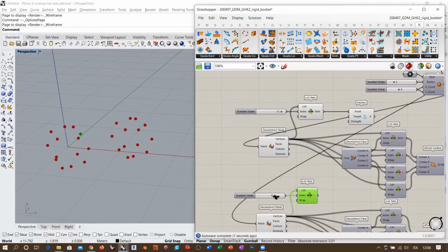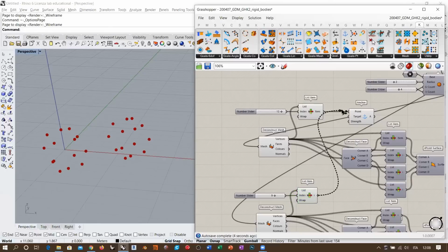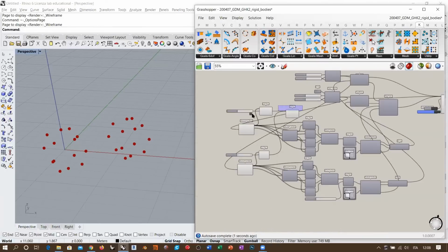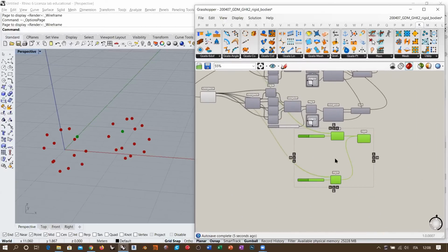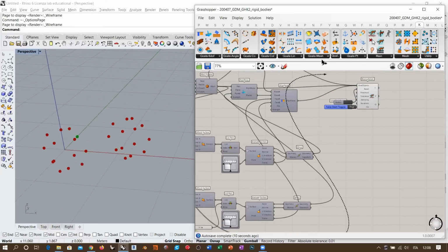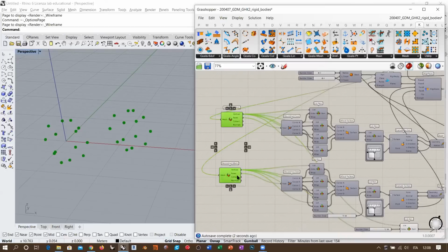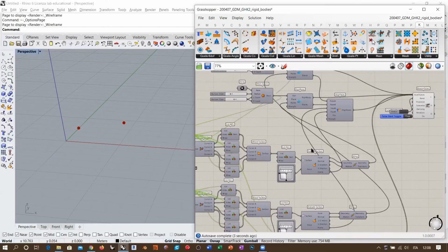So I'm going to use this point as an anchor point. Okay. And so this will also be an anchor point. I'm going to move all of these things to another position. So we have the anchor points here, and I will pass these anchor points to the goal object and turn off the preview of our deconstruct mesh.